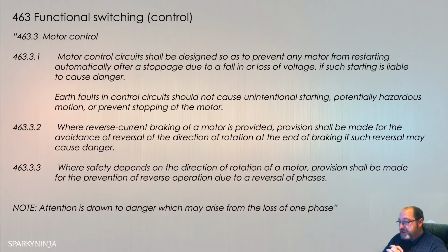Earth faults in control circuits should not cause unintentional starting, potentially hazardous motion, or prevent stopping of the motor. Where reverse current braking of a motor is provided, provision shall be made for the avoidance of reversal of the direction of rotation at the end of the braking if such reversal may cause danger.